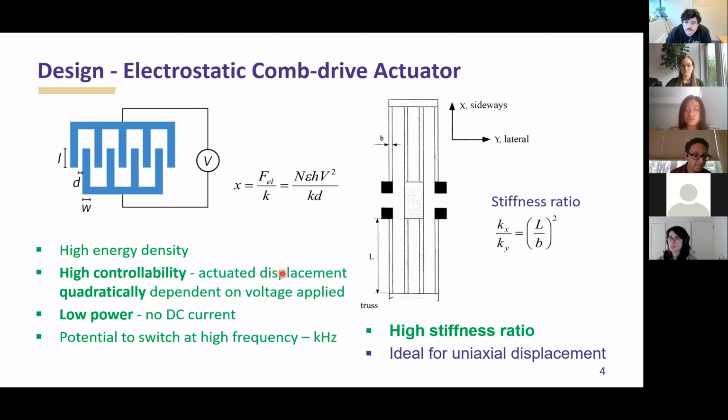So in order to create a lateral displacement between the two Alvarez metasurfaces, we have implemented a miniature MEMS actuator to electrostatically displace one of the metasurfaces relative to the other. A typical design of a comb drive actuator consists of two combs structured with interdigitated fingers, of which one side is usually fixed, while the other is connected to a compliant suspension.